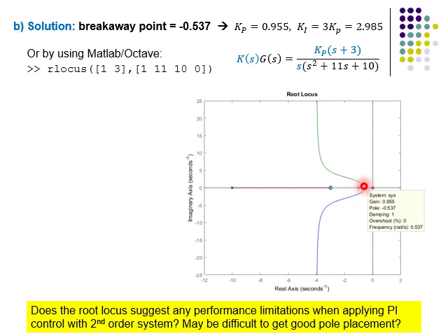And you can also see that if we try to increase Kp further, then the poles here become complex, so they become underdamped, and for large values of Kp, the damping ratio is going to become quite small as the poles move further and further from the real axis.